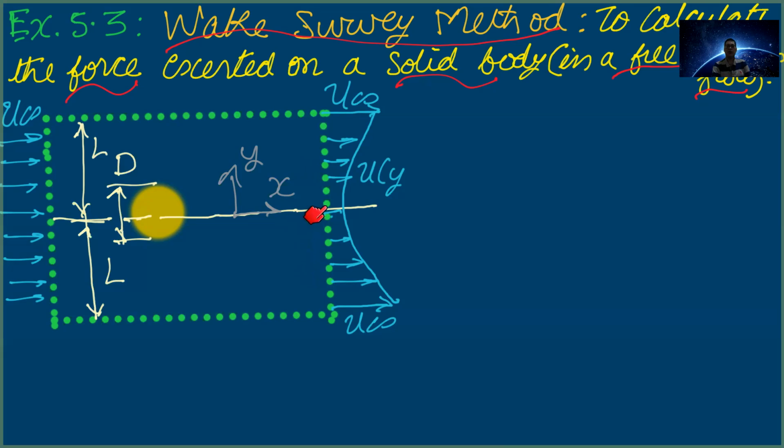I had mentioned in my lecture videos that for most of the problems, when you are given single valued velocities, then you can use algebraic form of the equations. But at certain boundaries of the control volume, if you are given a velocity profile, then make sure to use the integral form to calculate the mass flow rate and momentum flow rate.